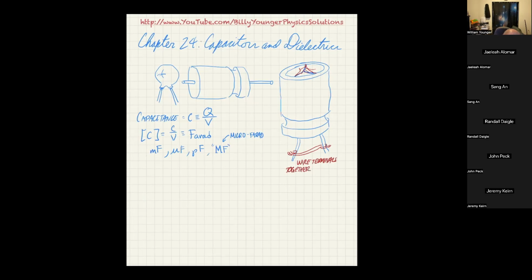That way, atmospheric changes and stuff like that are not going to cause charge to build up over time. And also, if someone happened to have charged it up during some process where they were using it and then didn't completely discharge it, it's not going to be holding that charge. Otherwise it would surprise you with a shock. So yes, you should wire the terminals together for safety.